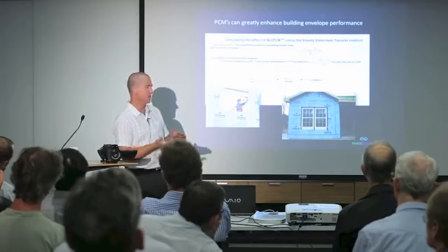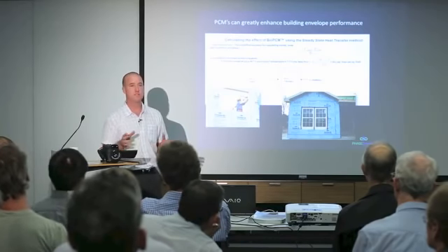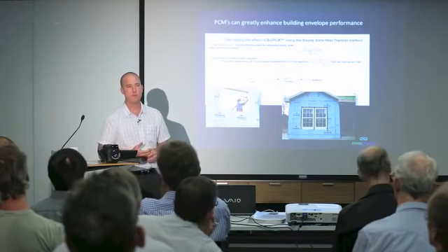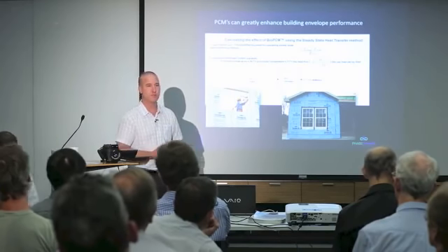It takes 20 minutes normally to stabilize, and then it takes about half an hour or an hour to do the test. We took phase change material and put it in there to see what would happen, because we wanted to get an R rating on it. Well, it took 7 hours to stabilize. And then the machine just came back with error, because the heat kept going in and it wasn't coming out, so the machine figured there was something wrong.